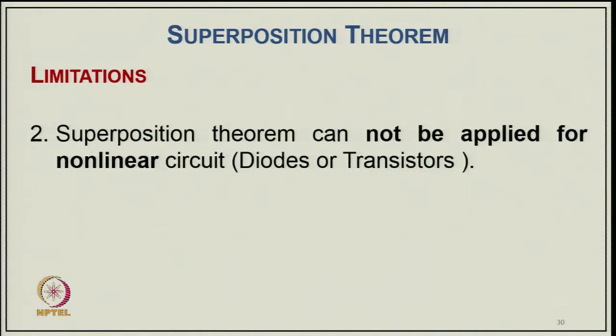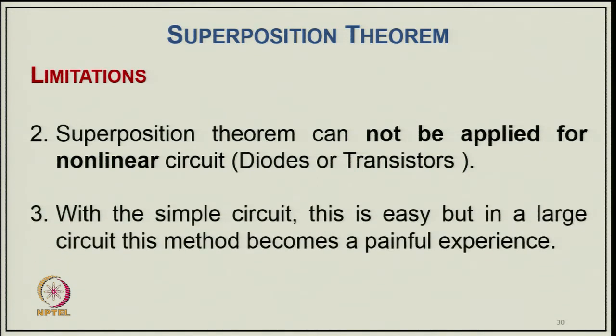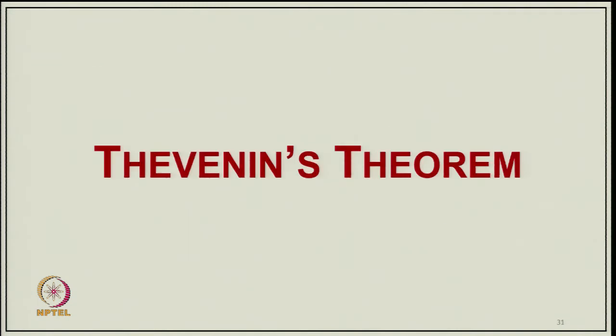Another limitation of the superposition theorem is that it cannot be applied to nonlinear circuits consisting of diodes and transistors, which are nonlinear elements. With a simple circuit this is easy, but in a large circuit this method becomes a painful experience. So, that is about the superposition theorem.